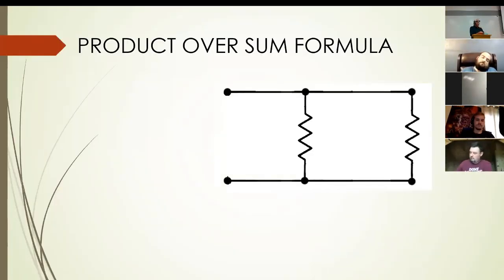So with parallel resistances, I've got a 60 here and a 40 here, but it is not 100. So how do we come up with that? Well, one method, it only works when you have two. Whenever I'm trying to combine only two in parallel, I use the product over sum.